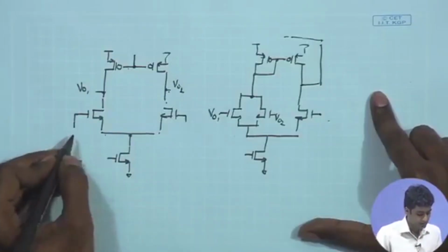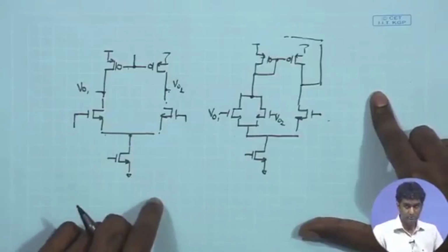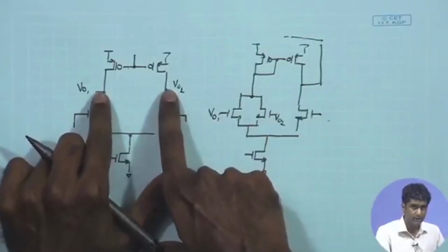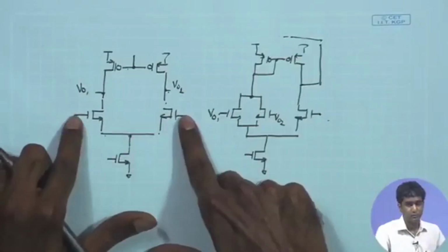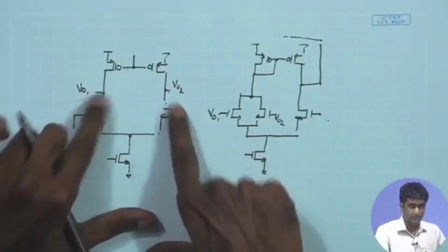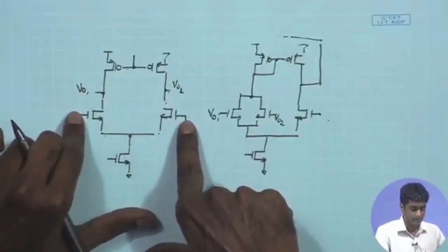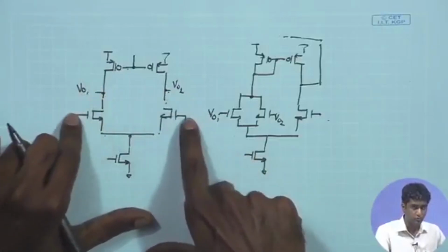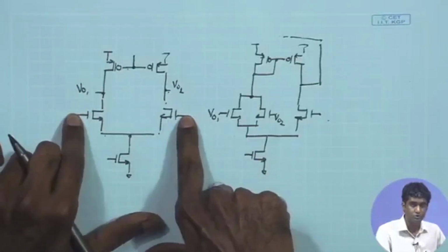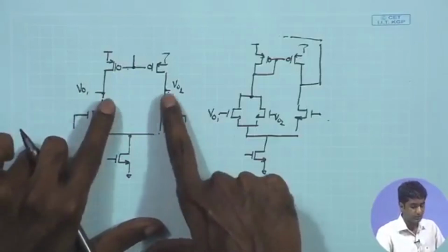And remember that when we are using the common mode feedback, we had set the output DC point with the help of common mode feedback, while for biasing the input we used a resistive divider, a large feedback resistor RF from VO1, VO2 to the input devices, and that ensured that the input DC point was equal to the output DC point.